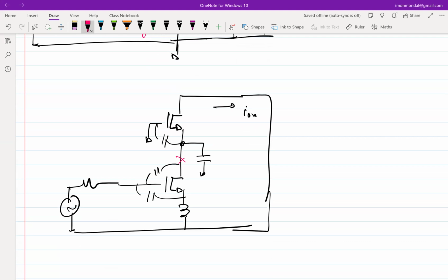If I assume that I have a RL, whatever be the value of the RL, most of the swing happens here. And here you have lesser swing, right? So even though CGD still exists, its effect is not as much, right? And also the feed through between whatever is connected to the mixer side to this node is even lower, right?